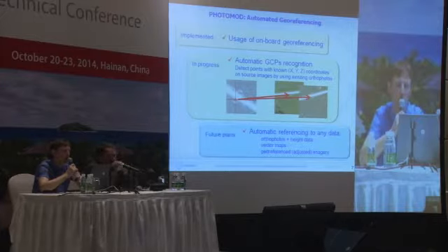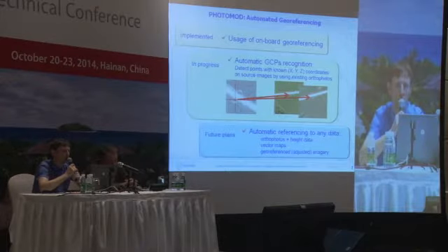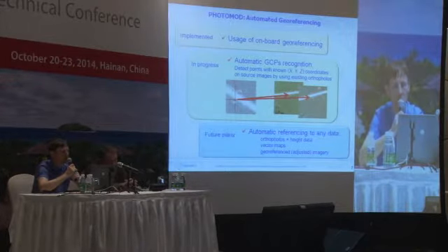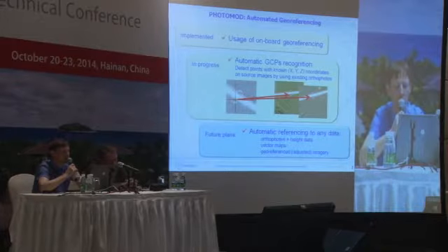What I mean here is the following procedure. For instance, you already have some good high-accuracy photo plans. You are aware of the coordinates of some of the ground control points, X, Y, Z, and PHOTOMOD, based on the catalog of these coordinates, is going to automatically locate these points on orthophotos and automatically find these points on the source images.